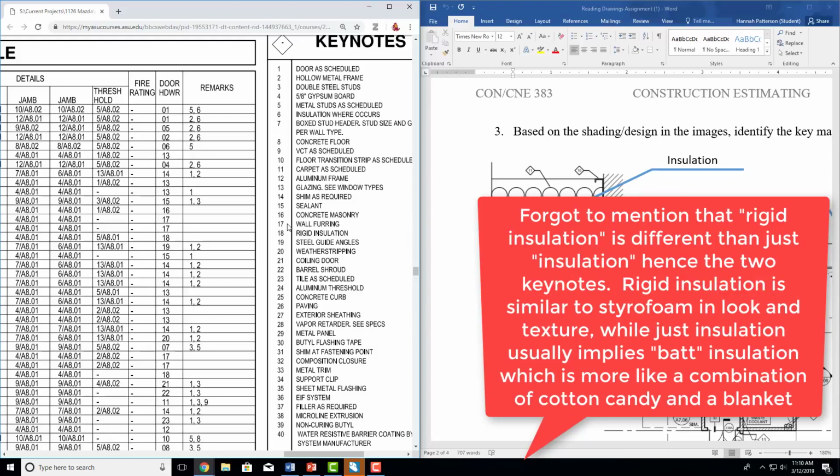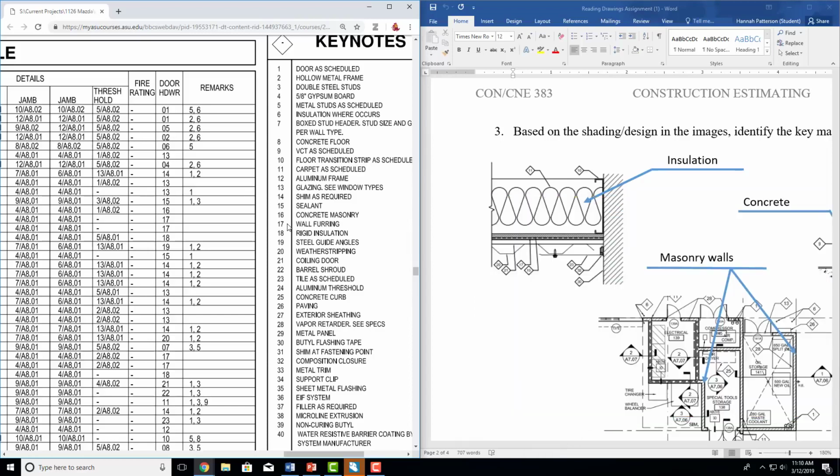So it's very common, let's say you have a masonry building, so you have those blocks everywhere, but you want it to be an office with drywall. In order to do that, you will do a one-sided wall which has no structural value and is only there because it looks good. It doesn't actually create a room. It's not a real wall.